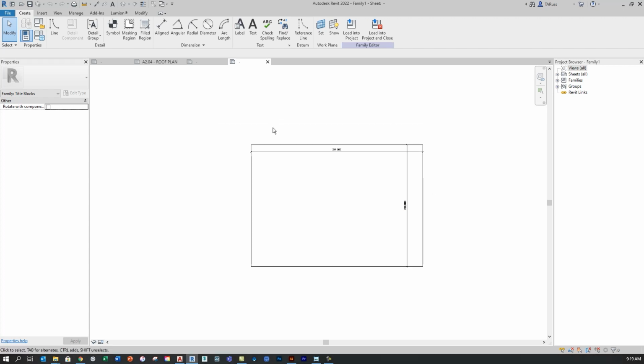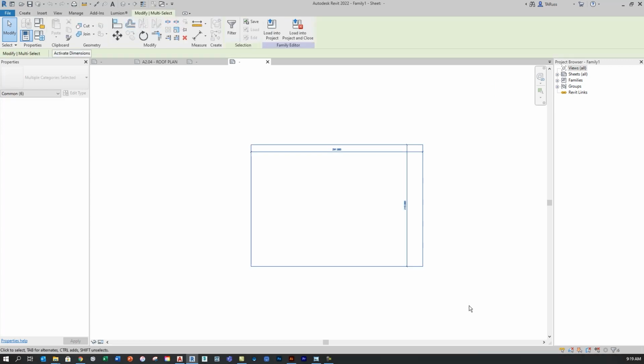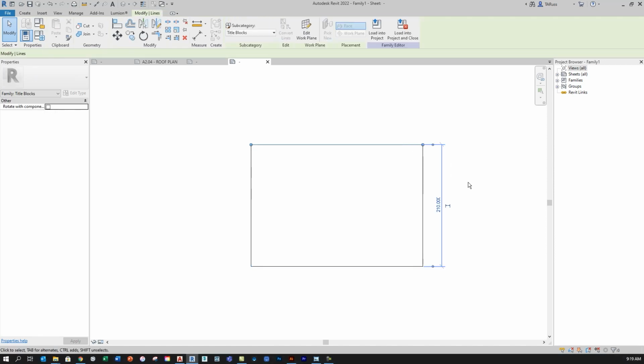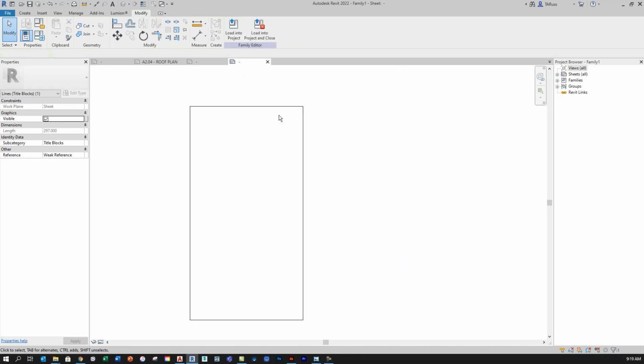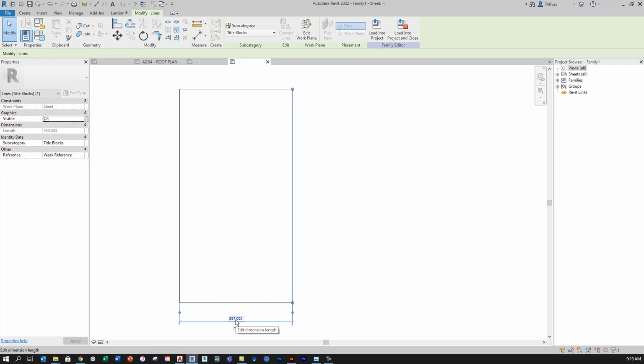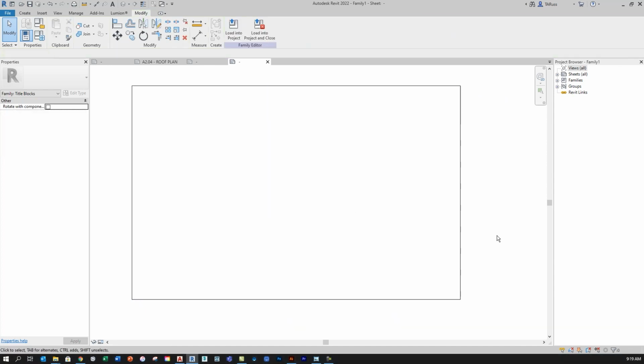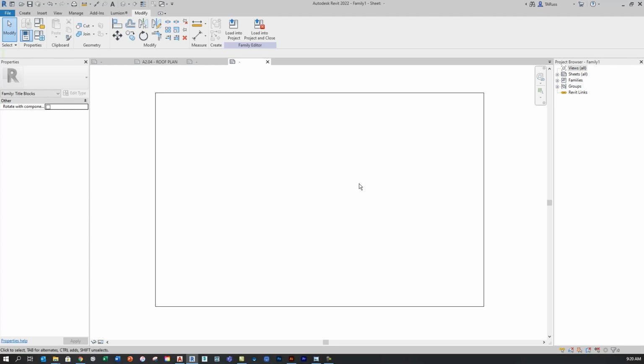And as I said, I started off with a really generic template here. And I'm actually just going to scrub everything that's already there. That was actually just a letter size sheet that was shown there. And I'm going to expand the size of it here so that I've got a 559 millimeter height. And then I'm going to change the width so that instead of 297, I've got 864 millimeters. Okay, so that's how this all begins. Those are the metric equivalent dimensions of an ANSI D sheet.